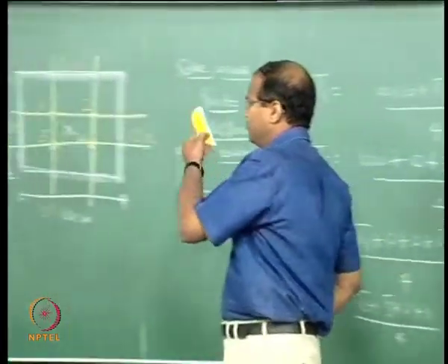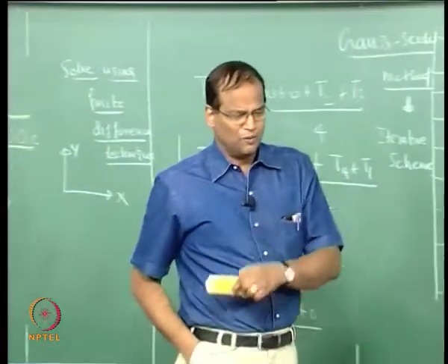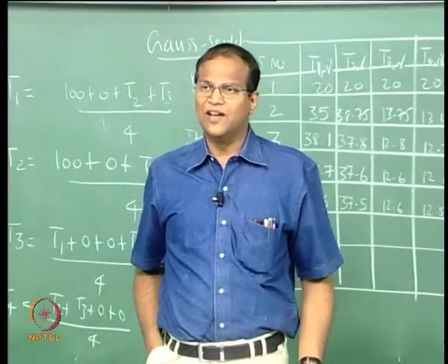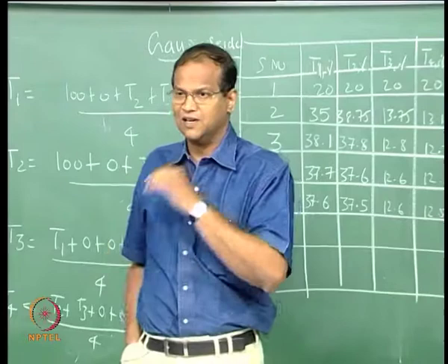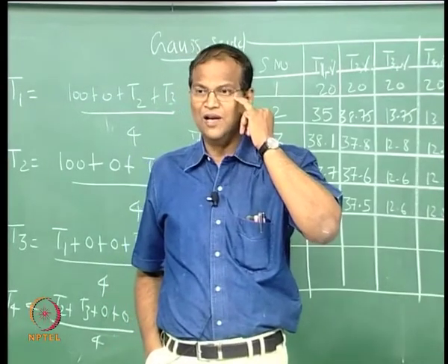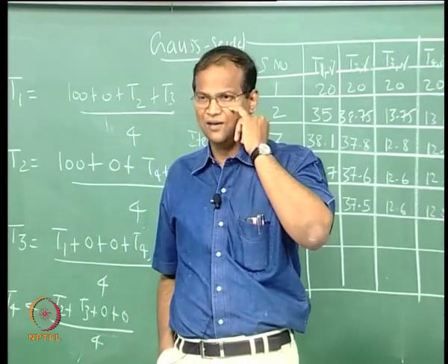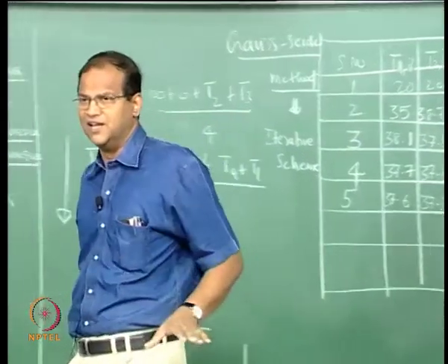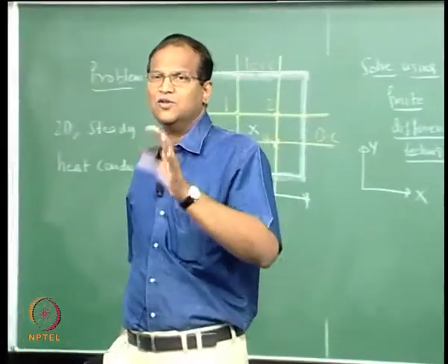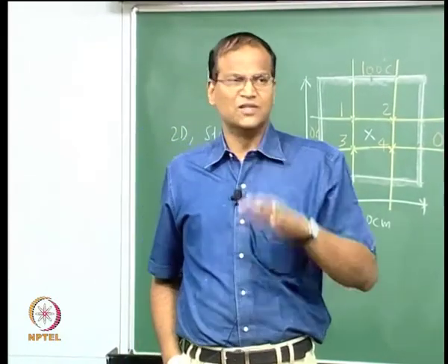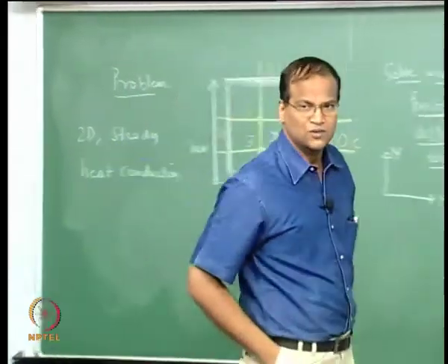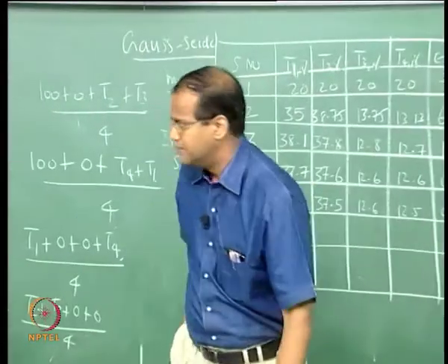Now we will see for a problem which is similar to this how we can apply the finite volume method, what the finite volume method is all about, then we will close our discussion on steady state problems. Then how do we handle numerically the one dimensional transient and steady conduction, basic ideas, same finite difference. So how the delta t and delta x must be chosen such that you have a scheme which is numerically stable, with that we will close, okay.